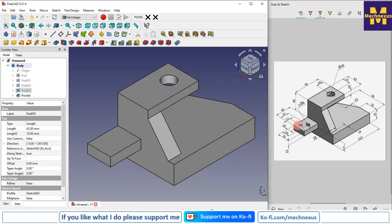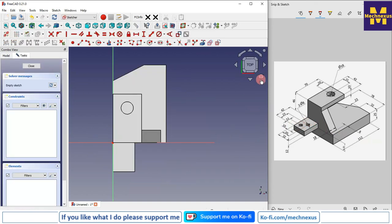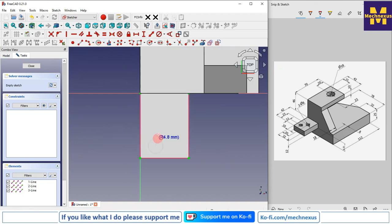And now we will create these two holes. So for this we will select the top face and click on the sketch, click on the isometric, and we will project the edges. So click on the project geometry, project this, this and this, click on the top. Now create the two circles, and these two holes are of diameter 8. So give the positions. So position is 10 mm from this point, 10 mm,